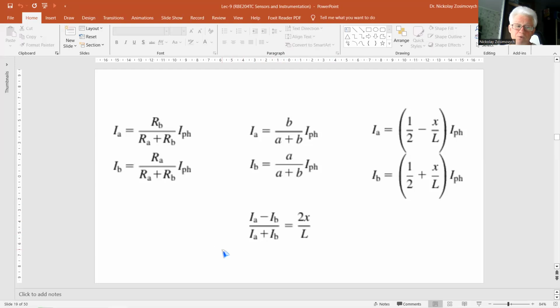So, to perform an intensity-independent position measurement, the PSD should be connected to an electronic interface for three signal operations: addition, subtraction, and division. A PSD is essentially an analog device.